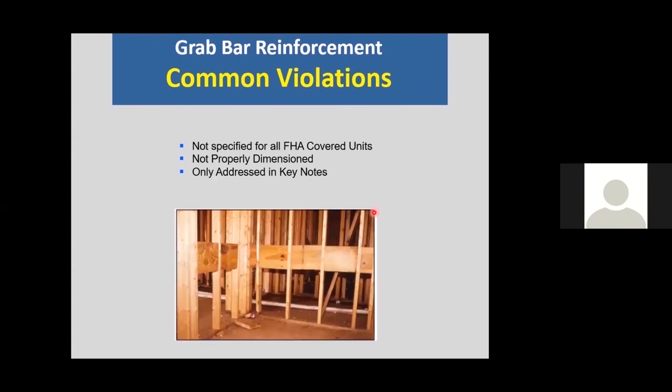The common violations we see, I would say primarily, is that reinforcing hasn't been planned for all of the units that are covered, or maybe it hasn't been planned in every bathroom. So these reinforcement requirements do apply to every bathroom in the unit, even if that particular bathroom isn't considered a usable one, which is what we'll be getting into.